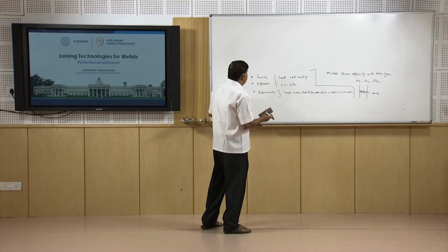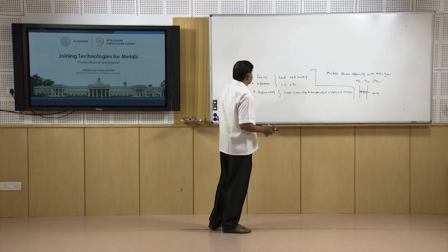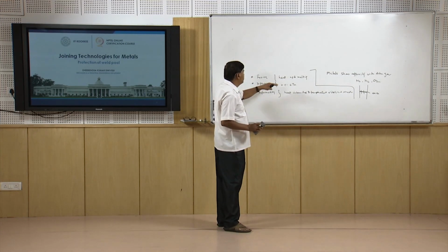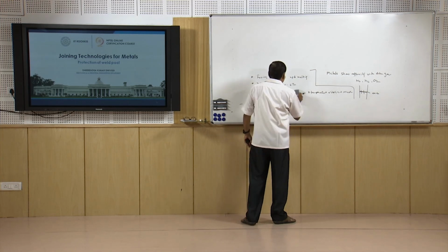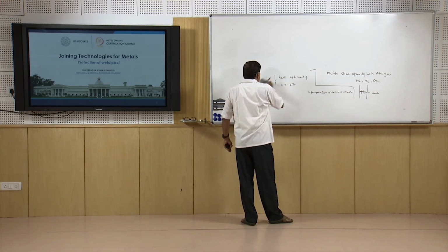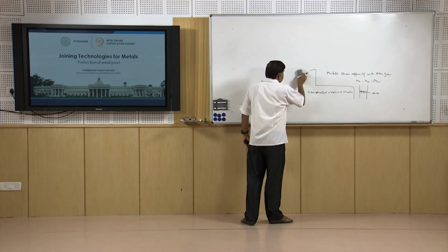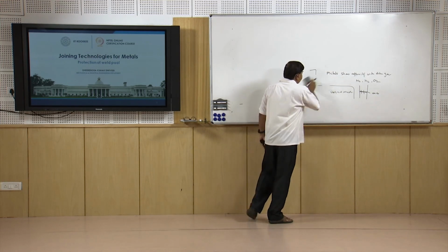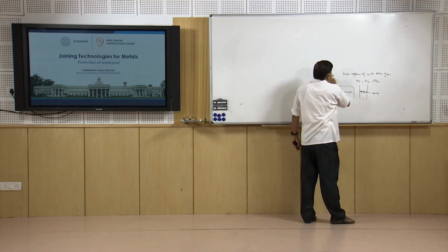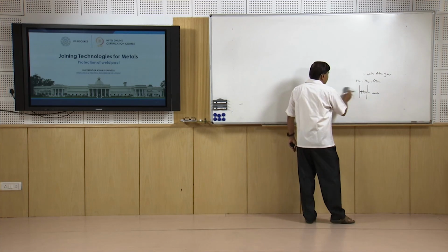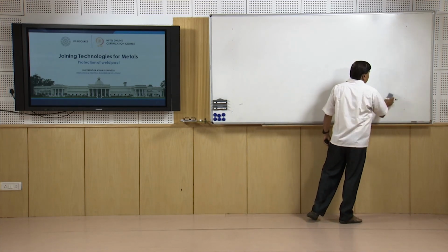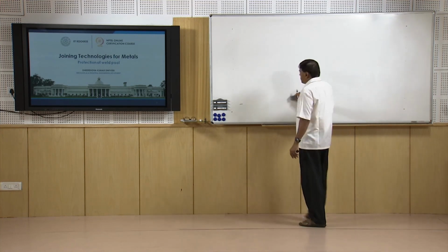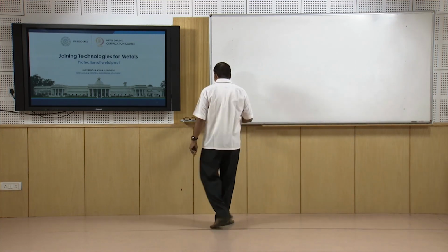So, now we will focus mainly on two aspects here, diffusion and fusion, because the problem of interactions of the atmospheric gases with the solid state process is not that much, unless very specialized metal systems are welded, like the titanium alloys, which may require protection.